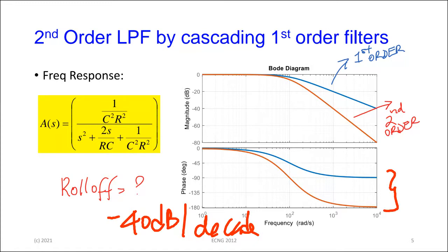But as you will notice, the cutoff frequency for this one is 100 radians per second, and the blue one is set up so it crosses at 100. The red, which is the cumulative second order function, also crosses the 90-degree phase at the same 100 radians per second. Don't worry too much about that phasing. We're going to talk about that this evening to explain it a little more fully, but this is the important one up here. Make sense?